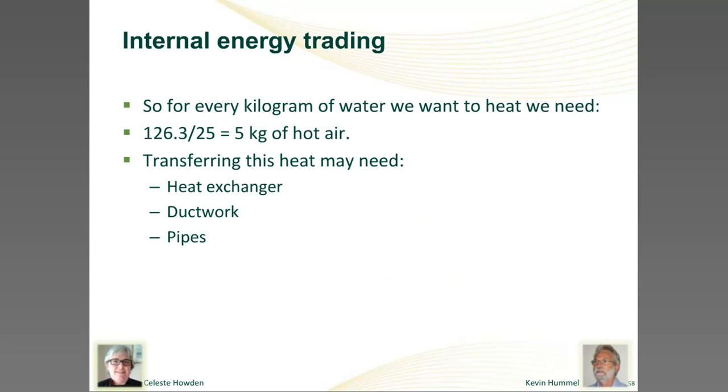So we've got 126 kilojoules that we need. We get 25 kilojoules from every kilogram of hot air, so we need 5 kilograms of hot air for every kilogram of water we want to heat. This lets us know whether the whole idea of transferring heat is worthwhile.